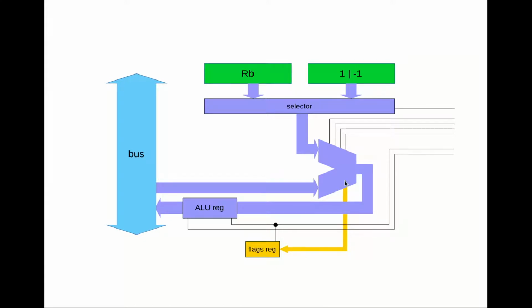Also the carry flag. So if we're performing an addition, for example, let's say we're cycling through all memory addresses, and so we're using the increase instruction. And so our second operand might be a 1 instead of the B register. So we keep increasing a register by 1, by 1, by 1. So we cycle through all the numbers. And at some point we'll arrive at 255. And then when we add another 1 to that 255, well, it's going to cycle back to 0 again, because we only have 8 bits. And when that happens, the ALU will set the carry flag. Because if we were performing a 16-bit addition, then we'd need to carry the result of that addition into the higher order 8-bit byte.